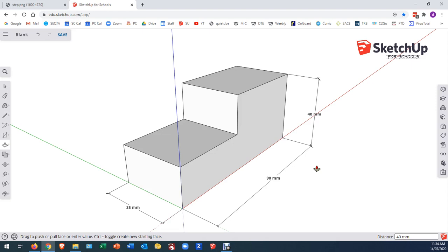So there's lots of different ways working from different surfaces to get the same stepped block over and over again, and some of them I've been using guidelines created with the tape measure tool. Some of them I haven't. If there's existing geometry or points on the lines that you can use, you do not necessarily need to use the tape measure tool, but that relies on the fact that this started on the midpoint. If I didn't have that midpoint, I would have to first create a point with the tape measure tool.